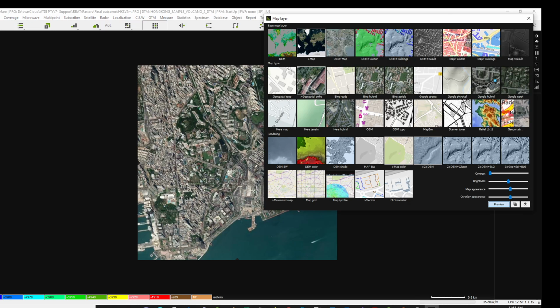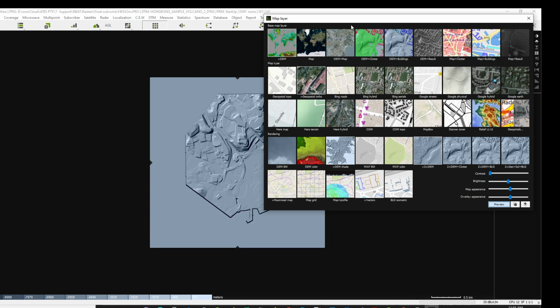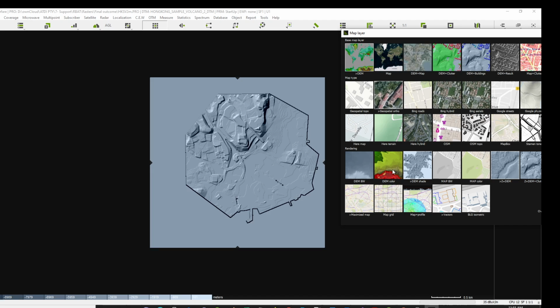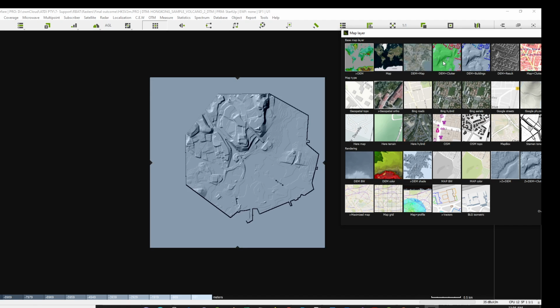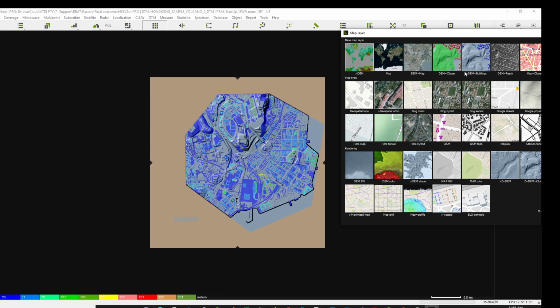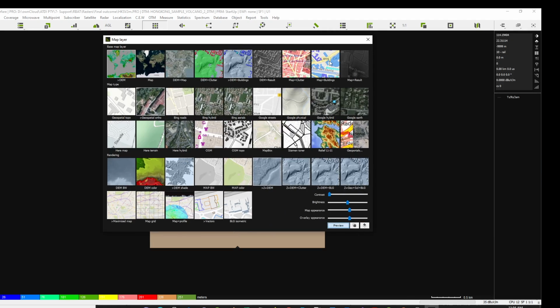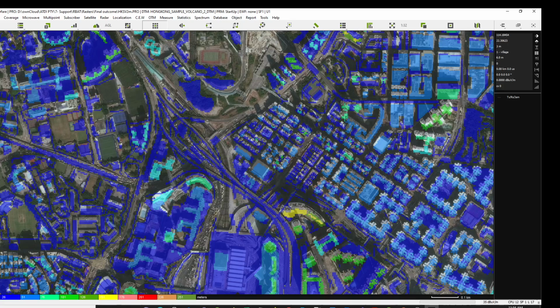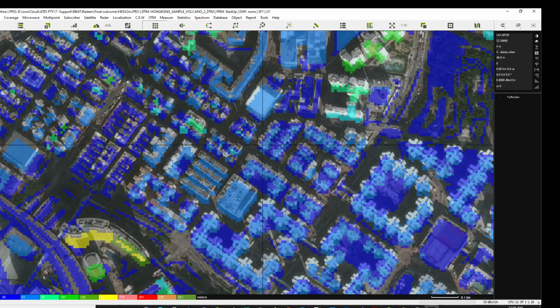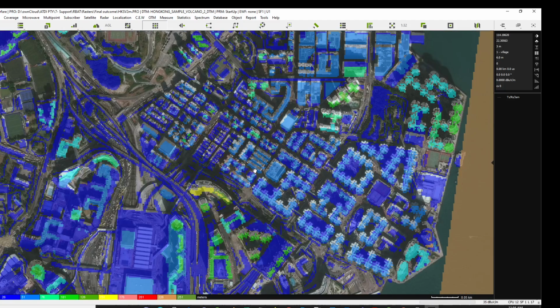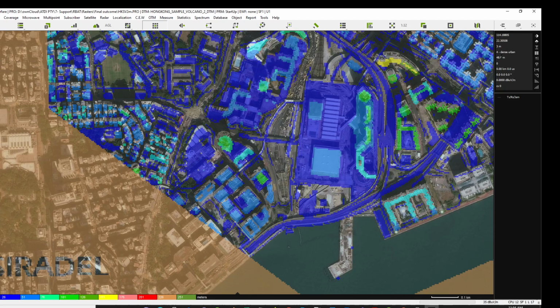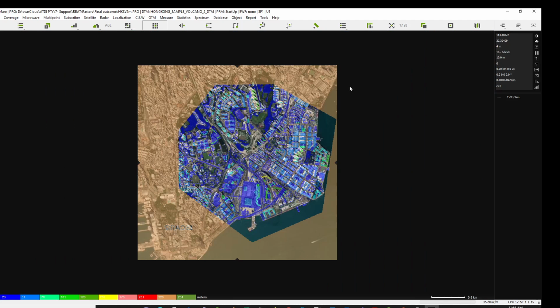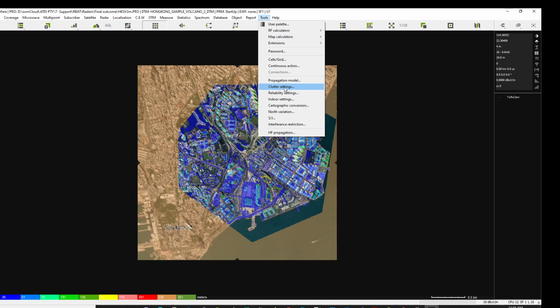And let's look at the rest of the layers. So here we've got the DEM. That's the DEM layer. So you click the DEM layer, and then you click this view or this view or this view. I prefer the gray. Now put the clutter on the top. That's the clutter. Put the buildings on the top, so you can see the buildings. And you can put the image with the building if you want. So you see it's a bit noisy here, depending on the quality and the resolution available. But you can see how it's working, and you can read here the elevation information. It's 144 meters.